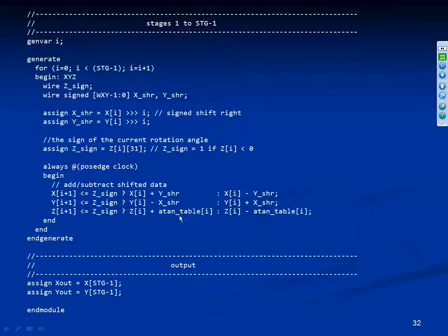Right. So these equations don't have any rounding in them right now. I'm not sure of the history on Mercury on the QS1R that was derived from it. It also didn't have any rounding originally, and I think there were some 90 dB down spurs or something like that that got eliminated when they put in the rounding. So it is, quote, way down in the noise, but there were discrete spurs that got generated from it.